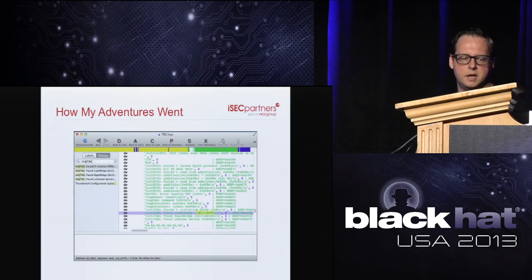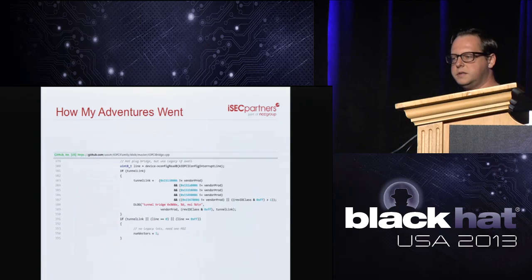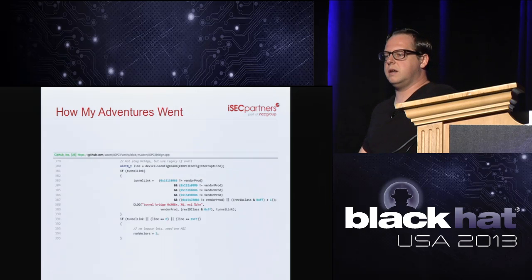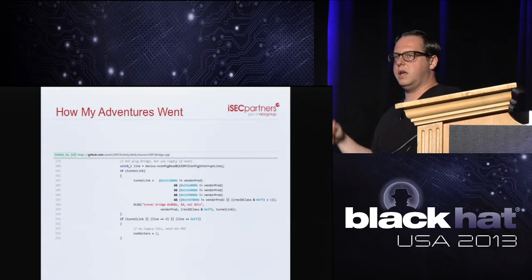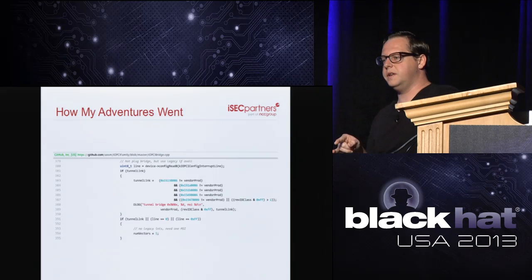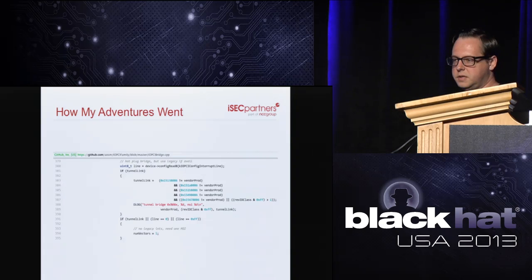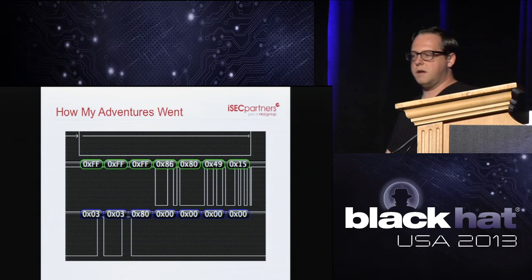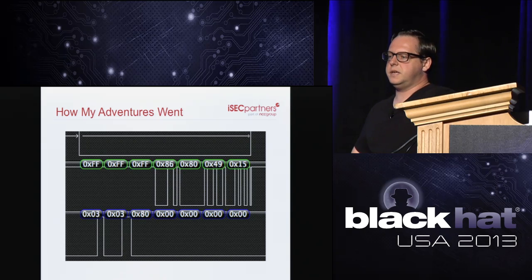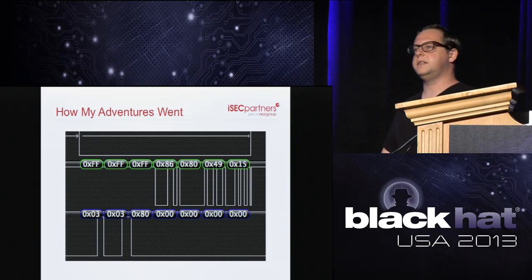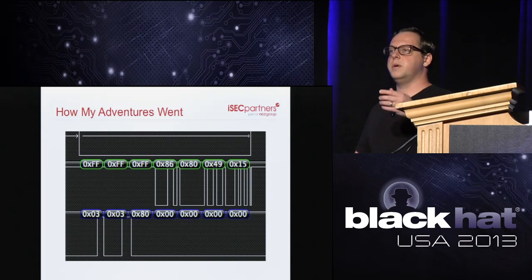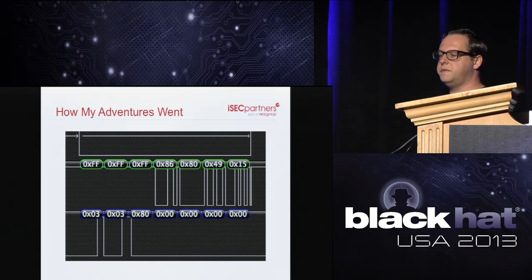We have basically two different descriptors for that. If we do a little Googling, we find only one file, and that file is IOPCIBridge.cpp on GitHub. Basically, this lists out that if these four identifiers are not the case, then go ahead and do some stuff. So now we are able to say with pretty high confidence, since two out of the four are listed in our EFI program, that this is probably the list of device IDs for all of the Thunderbolt family. Taking that, we look at our logic analyzer output, and sure enough, in little endian we see 86 80 49 15, or 0x15498086. This is traffic coming from our device up. So the Thunderbolt ridge that we're looking at has a device ID of 0x15498086.